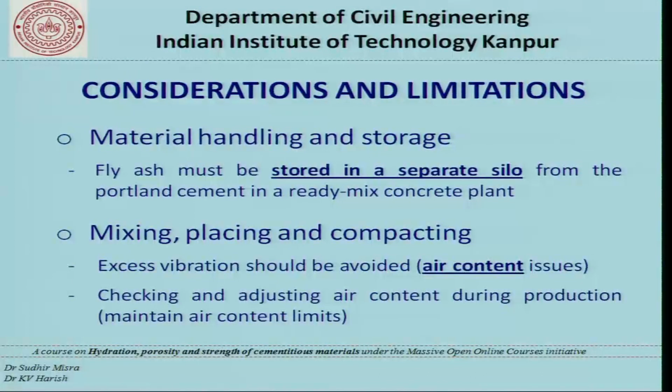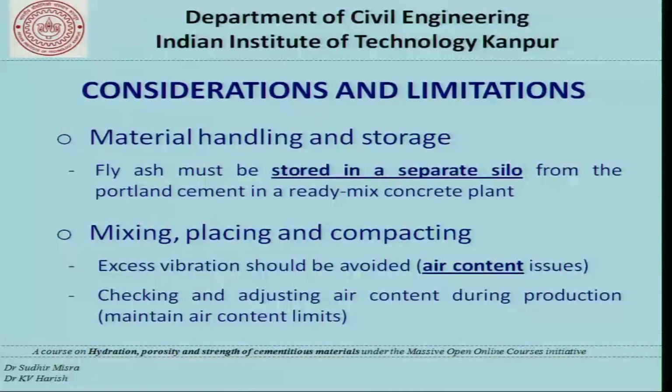Now the first limitation is that there is a material handling issue, because many times fly ash from different sources has a substantial amount of moisture. So many times we have to dry fly ash, and when we dry fly ash we again need energy, and that may become a little more expensive. That is one type of problem that we have when it comes to storage, because we cannot store fly ash that contains moisture because it will be sticky. So it will create a lot of problems when we want to take fly ash from that particular storage unit. For information, you should know that fly ash is stored in silos, like how we store cement in silos. The moisture content and other things can play a critical part when it comes to handling and storage.